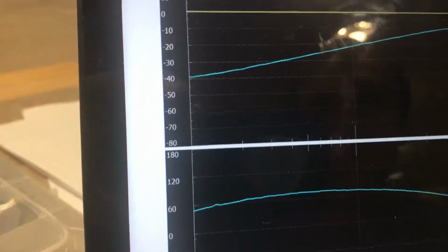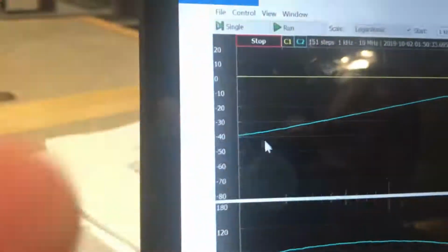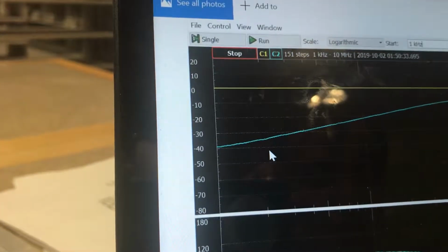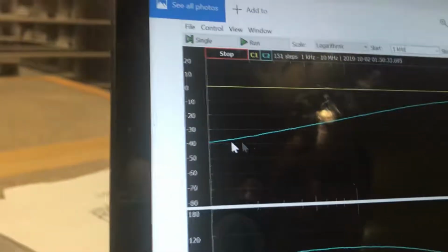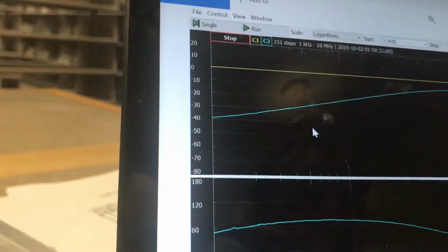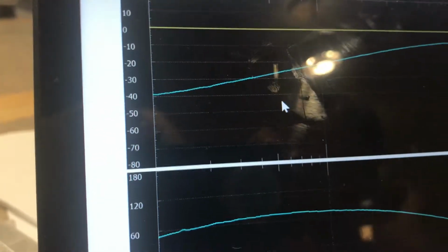So this is our common mode gain, 0.0068, and we can confirm that sort of using the frequency response. Here we'd start at negative 40. If we started at a little lower frequency, like 100 hertz, we would see negative 43 decibels, which is about what 0.0068 is in not decibels. But we start a little higher, we get a gain of around negative 40, which is close enough to the gain that we calculated using the square waves of 0.0068. Okay, so that is